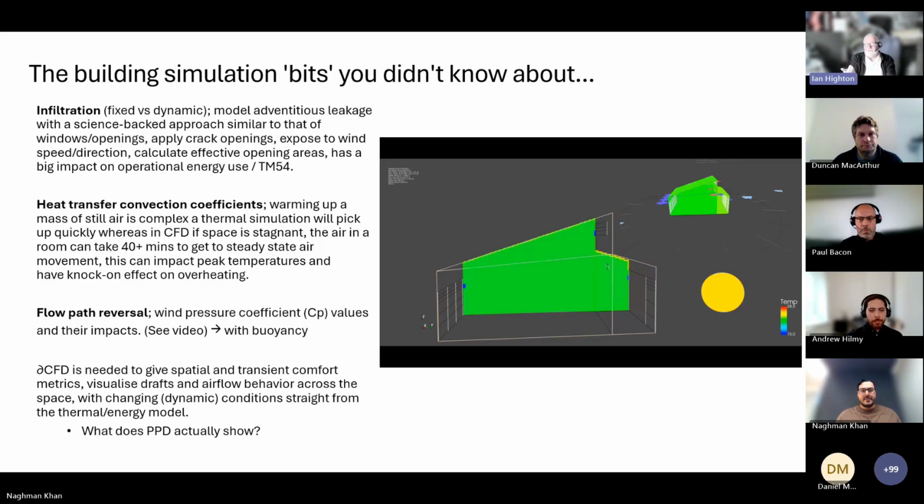Yeah. And I think you've upgraded the utility, haven't you, Andrew? Yeah, we have a little tool to help you do the wind-driven infiltration. You can take an air pressure test result, and it'll give you the crack area that you need to apply to your window frames to model these leakages in the facade and throughout the building, so you can get the proper infiltration flow. If you were comparing against measured data, you get much closer to reality. It's quite a significant impact.